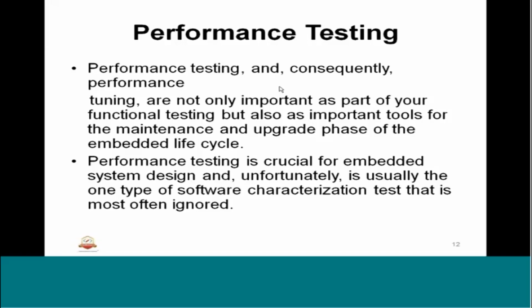That is why it's very important to have an understanding of the performance of the embedded system. Accordingly, we need to have testing mechanisms, especially on the memory, speed, timing, and the load of the unit. And we should use analyzers such as performance analyzers and map files. Probably we'll try to touch base on a simple map file to have an understanding of what it does. But basically, it is part of the embedded system course, so I'll try to address it in a future class.